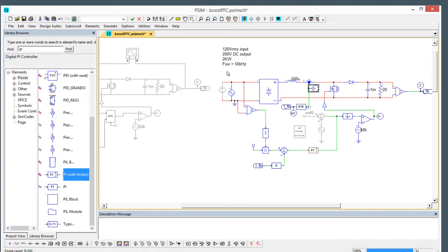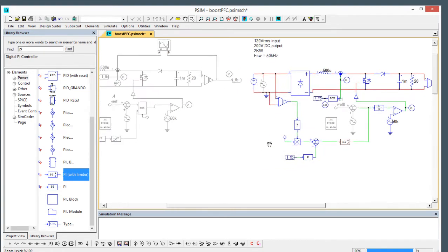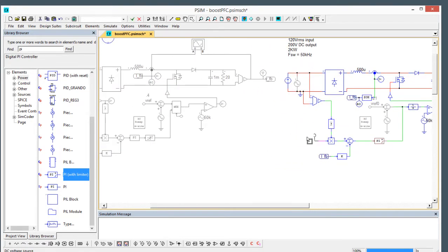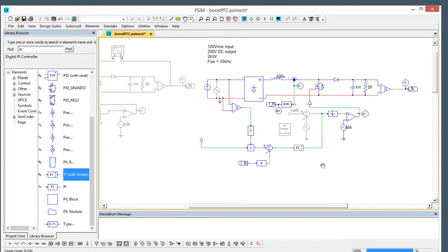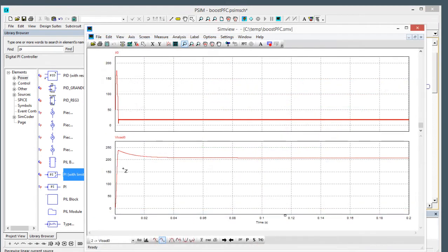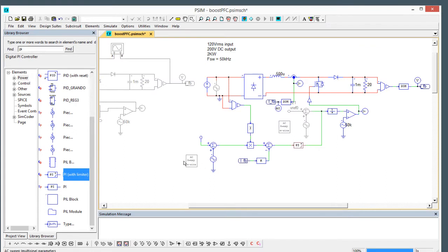So let's go ahead and close some voltage loops. What we need to do now is do the exact same thing that we did the first time through, with regards to the frequency sweep, but this time we're going to do it to the output voltage. So we'll rejoin the video again when I've got the AC sweep set up for the output voltage. Okay, so I've rerun the steady state voltage. What we need to do is figure out where steady state occurs, and it looks like definitely by 100 milliseconds we're in steady state, and we're going to need that again in the AC sweep block here.